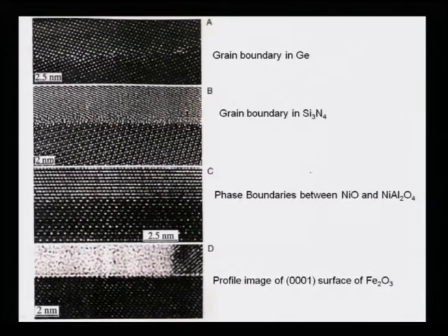This is the dark field image of Au4Mn. What you can see here are all the black and white dots of atoms, where you do not know which one is what, but you can see the antiphase domain boundaries marked by these white circles. Also, you can see a huge number of distortions in the picture. Next one is taken from a set of pictures by many authors, some of it ours. So, we can actually image a grain boundary of germanium. You can clearly see it consisting of dislocations at different intervals. Each one has one dislocation, a low angle grain boundary consisting of a parallel set of dislocations.